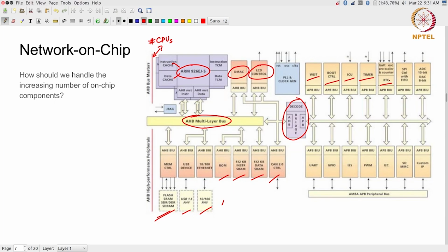In 1995, for example, having a 100 megahertz processor was a big deal. By 2000 they had hit 1 gigahertz, but then it started slowly saturating. They went up to 2, 3, reached 4. At that point they found that the power bottleneck was such that you simply can't go to higher frequencies. So then instead they said, let's play the parallelism game.